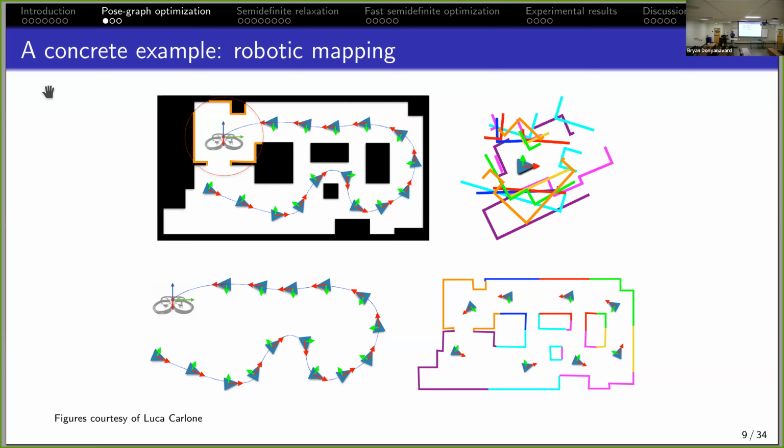And if I think about why that is the case, what is really going on is that the apparent motion, or the shifting of the location of that landmark in those two scans, is actually caused by the motion of the robot itself. So if I think back through this collection of scans that I've collected so far, anytime I can recognize that I'm looking at the same object across multiple different scans, that recognition tells me something about the relative motion that the robot underwent between when those two scans were taken.